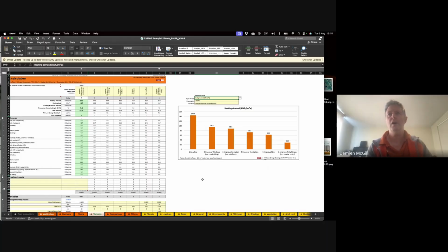Your windows are where your heat comes from, your solar gain comes from. It's also where your biggest losses come from, and it's also generally the most expensive component on the house. If you're doing a code minimum set of windows, they're saying that they're 0.5, but they're more like 0.4, 0.41, something like that.